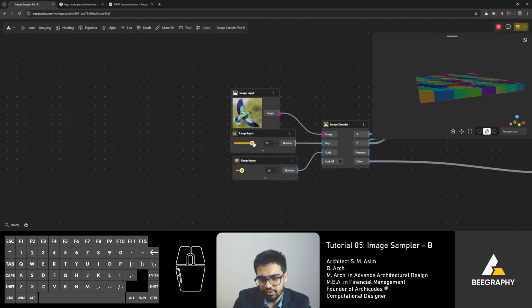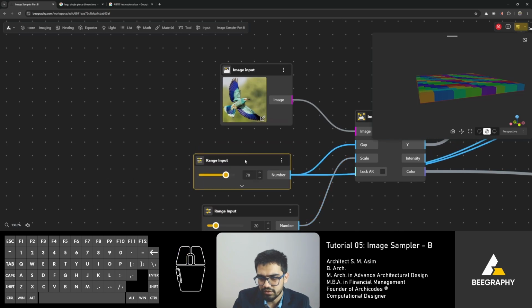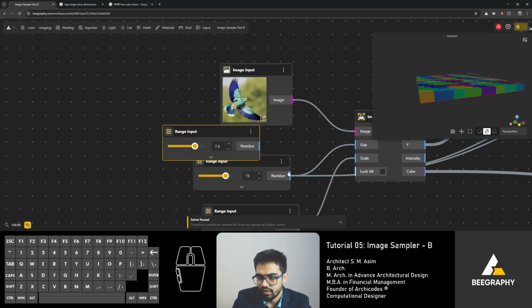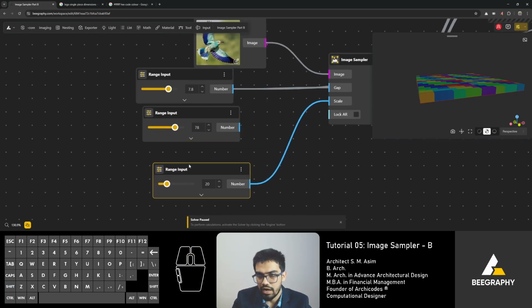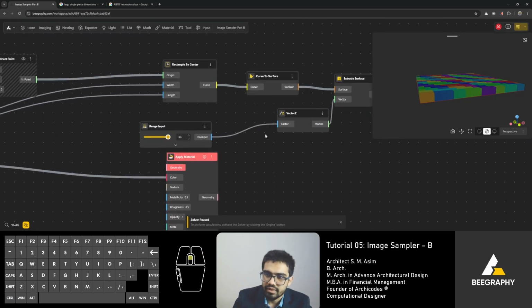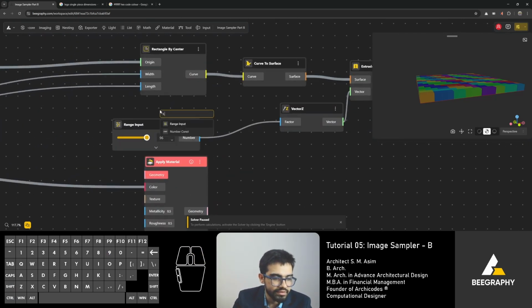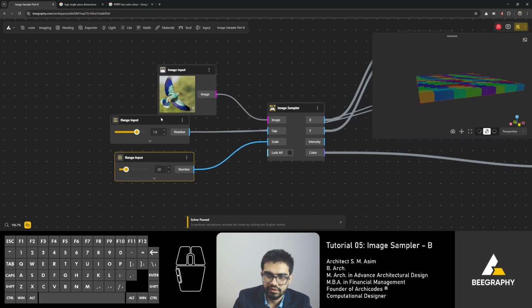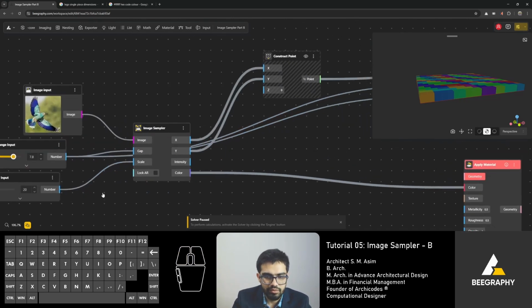And just actually to show you that anything is fine, like even this works, or even small order number will work as well. Let me stop the solver. Yeah. And I'm gonna do Control Shift to transfer all of these outputs to 7.8. And this one will be 9.6. And yeah, just remove the bigger order numbers. As soon as I turn on the solver, everything will shrink by 10 times.